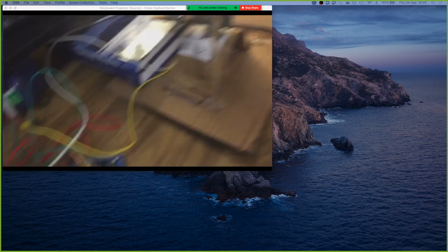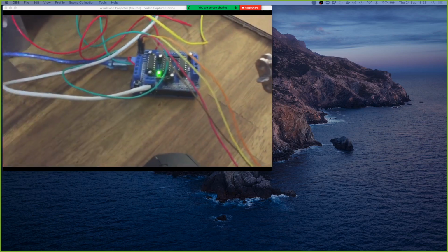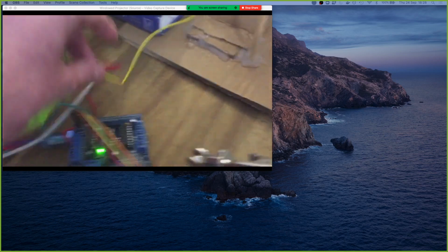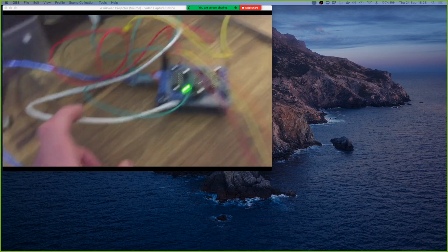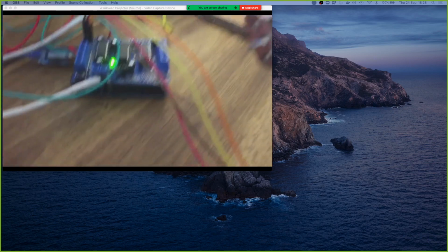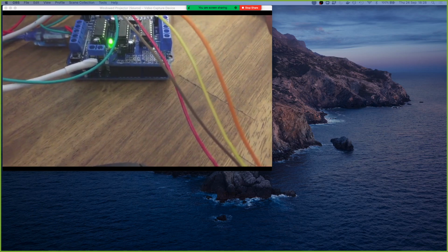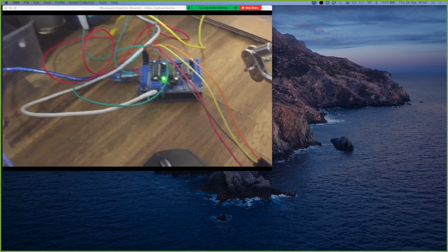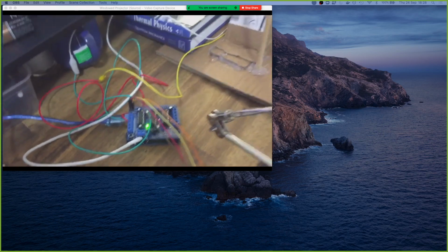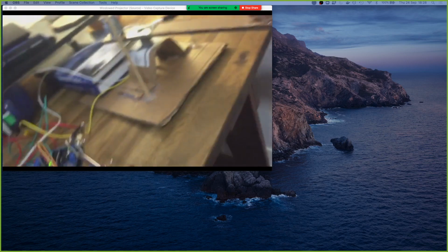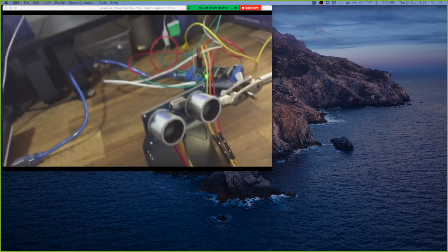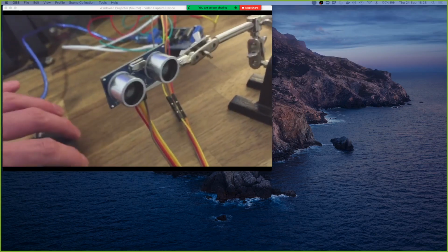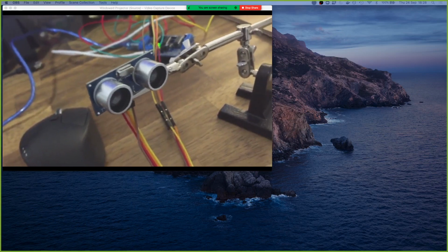I've got the motor attached to my Arduino with a motor shield on the top to drive that particular motor. That's the cables going off this way. I've got the motor driven by a 12-volt source. The Arduino sits underneath, and the Arduino will go by the blue cable back to the computer to upload code to it. And also, I've got one of these ultrasonic distance sensors here, which is connected to the Arduino as well.